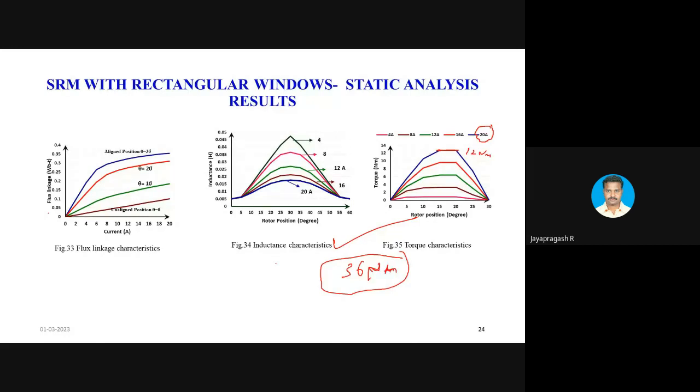So we have to use a gear arrangement to increase the torque by 3 times. If the torque is increased by 3 times, the speed will be reduced by 3 times, so that the power can be maintained constant. The gear is very similar to transformer action. That's the idea. So using the gear, we can increase the torque to 36 Newton meter, and I can run the machine.